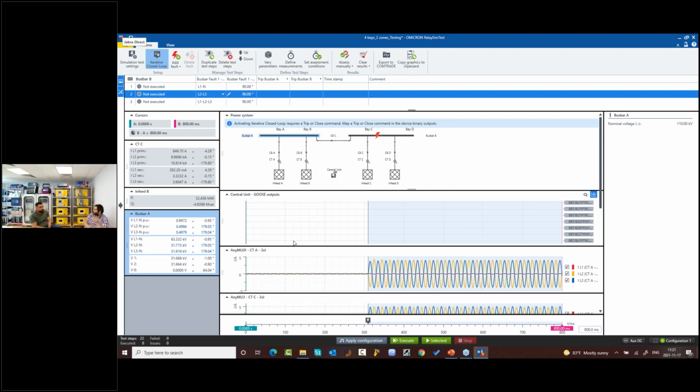And once you have a probe or test file, you can connect to CMC to generate that signal to be injected into the relay to perform the full test of your protection system. So we can say that if I'm a protection engineering department, for example, I can simulate any kind of fault, then export it in a ComTrade file.